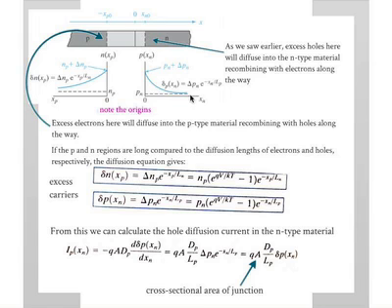Okay, and this diffuses and recombines at the same time, right? Remember, that's the diffusion equation we solved before. The excess holes here will diffuse into the N-type material, recombining with electrons along the way. It will form an expression which looks like that. This excess number is equal to delta Pn times e raised to minus xn over Lp, where Lp is the diffusion length. Right? It's the average length before a hole diffuses, essentially.